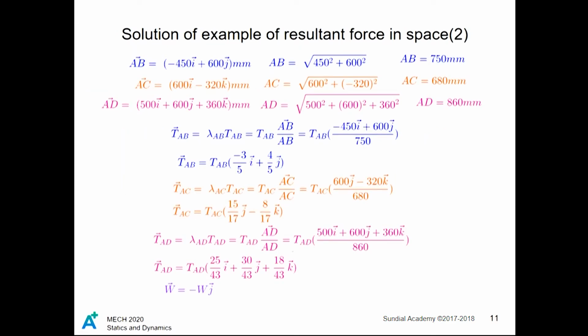From this information, we can find the trigonometric ratios of each cable's tension and break each cable's tension into rectangular components. Since the system is in equilibrium, the net forces in all directions should be equal to 0. We use the dimensions here to generate unit vectors and to help directly solve the force magnitude variables. From this, we use vector addition to form a system of equations to find the unknown values in AD, AC, and W.